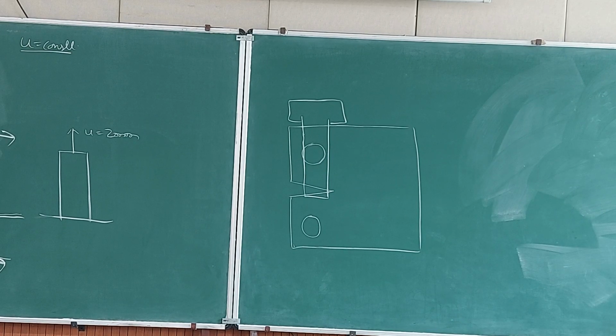Why? You also apply force at some rate, right? Sir, we are not controlling force. The initial stage when you are applying force or displacement, in both cases you will take some time. Whether you apply a 2 millimeter displacement or a 6 kilonewton force, in both cases the machine will go from 0 to 6000 Newton. That part is done. Once you apply the load or displacement, then you put the sample inside the furnace, switch on the furnace, let it go to the temperature, then thermal expansion will take place. Okay? And after that you start counting your time.